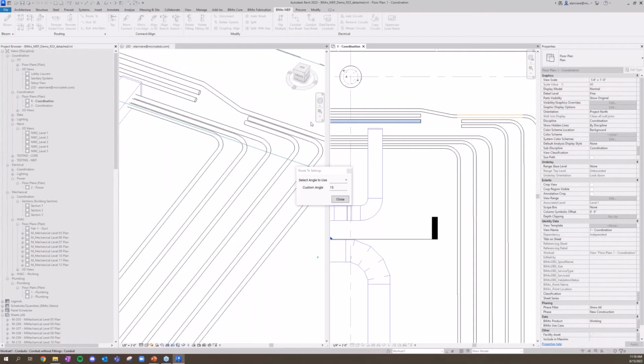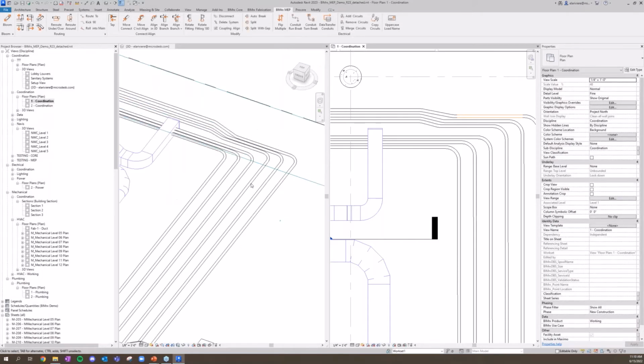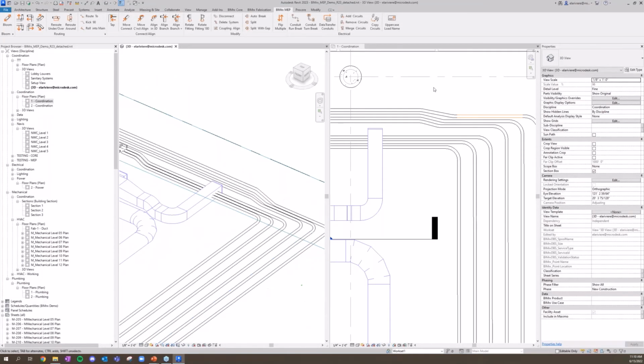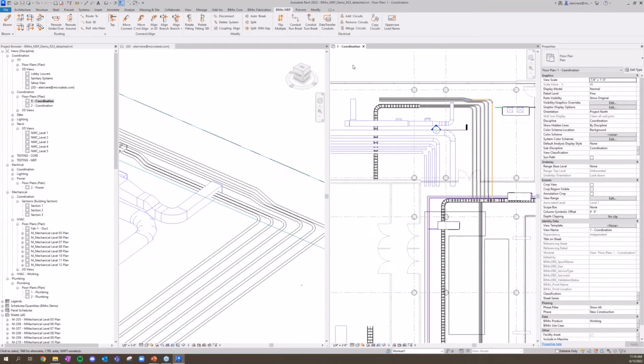Though, I'd love you to notice exactly what this route 2 is doing. Connecting those different conduits with built-in exact angles, and I can do that in 2D or 3D, right? Really nifty stuff. So even though that elbow parameter isn't tracking because we're not using elbows, we do have another command that allows us to do that, the data transfer conduits.